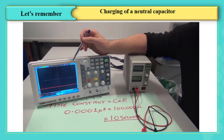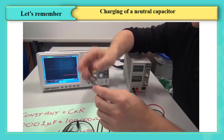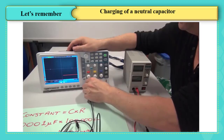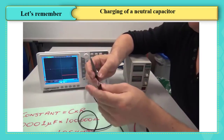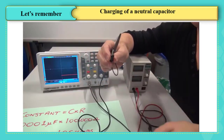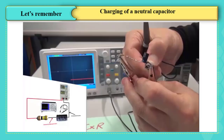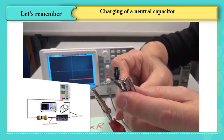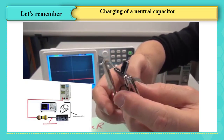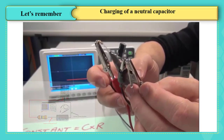And here we have the oscilloscope, and we're going to use the oscilloscope to measure the voltage across the capacitor. We need to connect the scope. We have two ports here, channel 1, channel 2. It's simply push and twist. The probe itself has a ground clip, and that will connect to the ground of your circuit. And the probe itself connects to the other side of the capacitor like that. And that is all you need to do to set up the connections for this circuit.